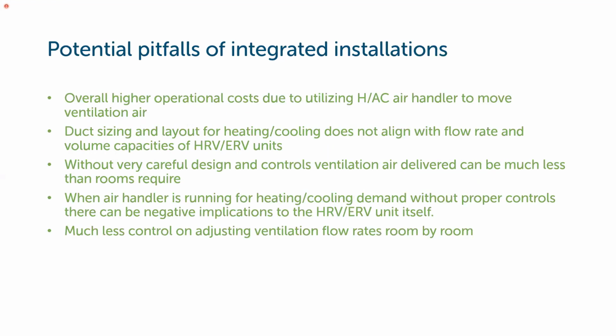But you have to be aware of what the equipment can do independent of the duct system. HVAC systems for heating and cooling move air in a way different than what HRV and ERV systems are designed to do. They're two different boxes with two different flow rates and two different intentions. So when you combine those two pieces of equipment to do a single purpose, you have to be careful in your consideration of how they're going to end up functioning in the end.